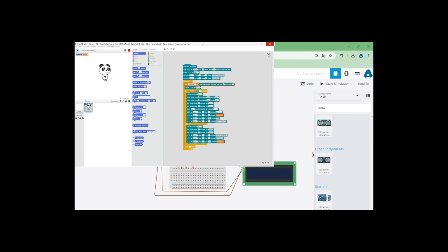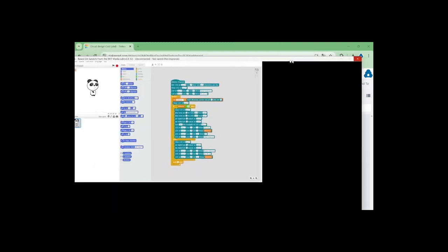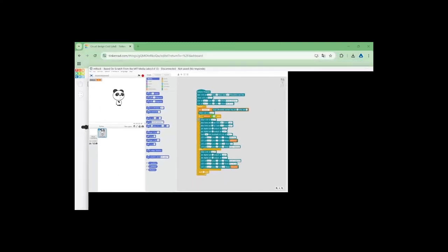The functionality we want to use is always the same. At the end it uses a forever control element where we read the trigger coming from pin 4 and the echo coming from pin 5 that we were defining.